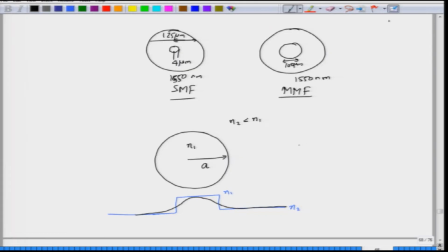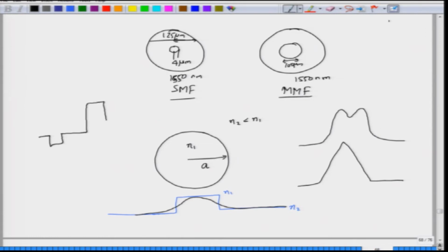Some specialized optical fibers have profiles that would look in this manner, and that would be in this way. There are what are called triangular shaped profiles. Then you have profiles with what is called a trench. So, this is one trenched step index fiber. You will also have a trenched but graded index fiber. These different fiber refractive index profiles, which correspond to different types of fibers, are all used in different applications. When you deal with fibers, you deal with a property called dispersion.